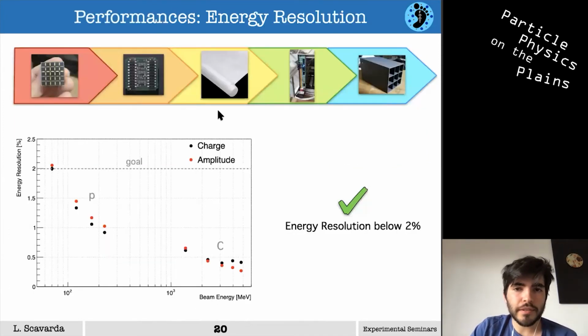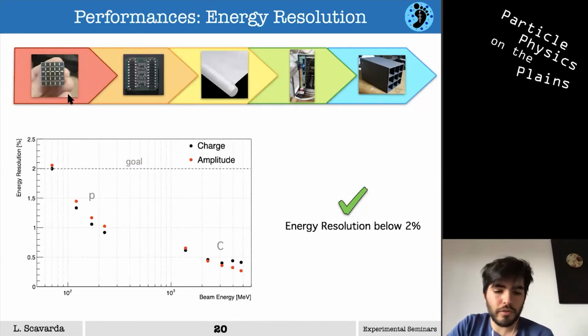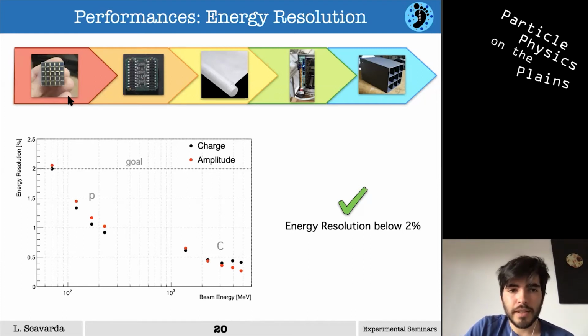So thanks to all these pieces, we have made all the design choices for our calorimeter: the silicon photomultiplier, the readout board with the same dimension as the silicon photomultiplier, so the design is really compact, the wrappings, the ADC, the digitizer. I didn't say anything about this, but we have performed a lot of tests on the digitizer in order to understand if we wanted to do pulse shape analysis or not. And finally, the mechanics. With all this information, we have achieved our goal.